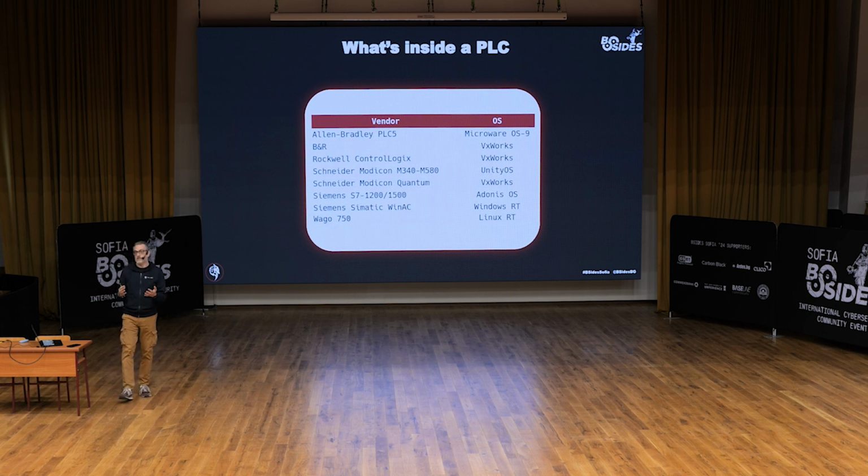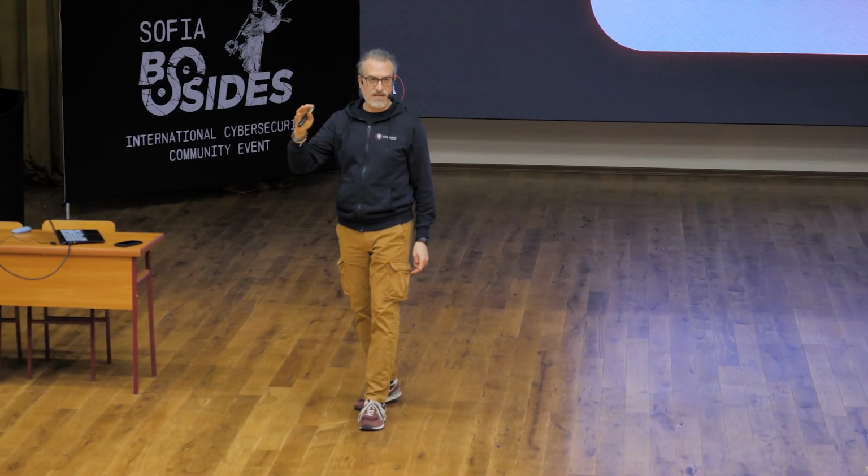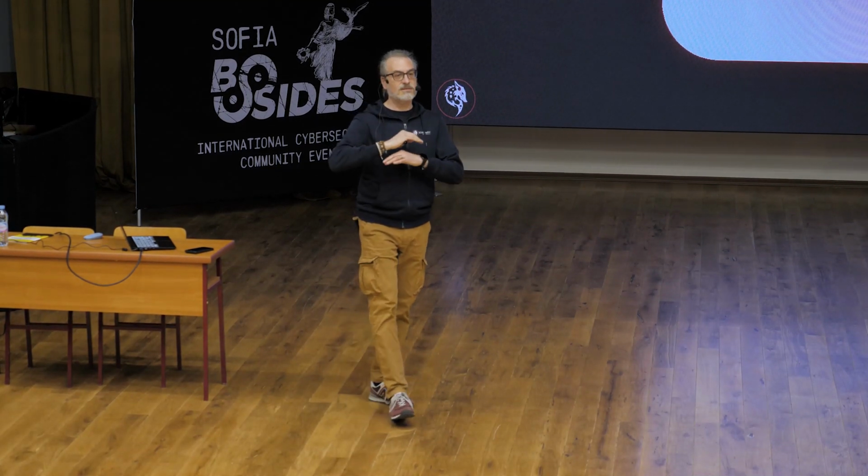That means that you can consider a PLC exactly as a PC, with an embedded system, without keyboard, without HDMI port, without mouse, in certain cases with some USB port, with some memories, with real-time extension. This is a very big difference. This embedded Linux system is a very limited version in order to have the best performance possible in terms of real time. Consider that the execution cycle of the program inside a PLC can take more or less 10 milliseconds, 20 milliseconds, in most cases, maybe 80 milliseconds, but no more. And every loop is executed every, I don't know, 10 milliseconds for 30 years.